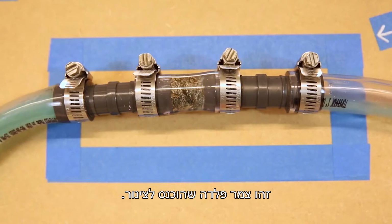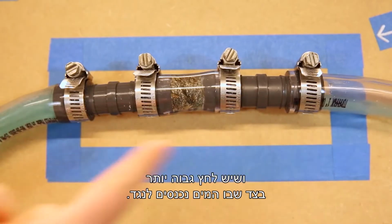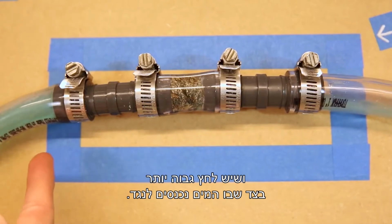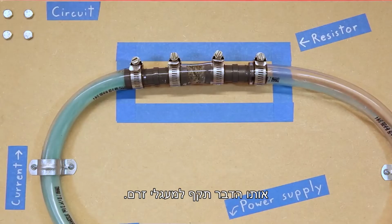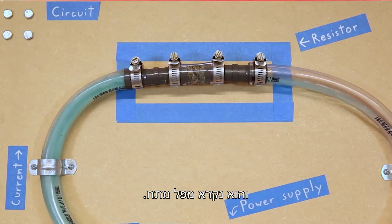This is some steel wool shoved into a tube. You can see how all that material resists the flow of water, and there is higher pressure on the side the water is entering the resistor. The same holds true in electronics. There is a voltage difference between the ends of the resistor when current is flowing through it, and this is known as a voltage drop.